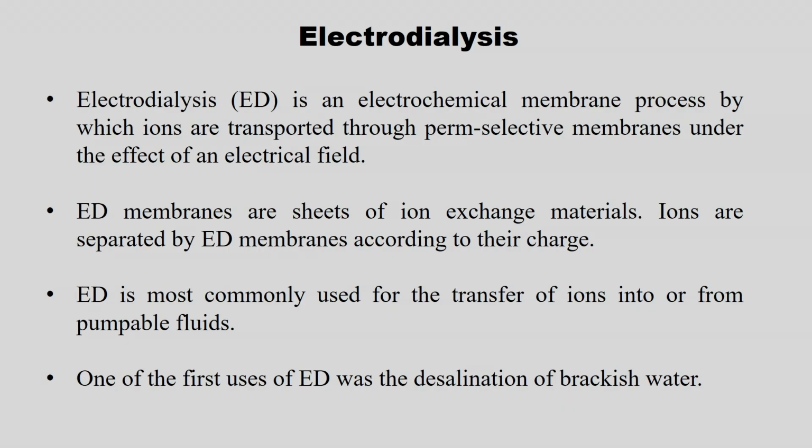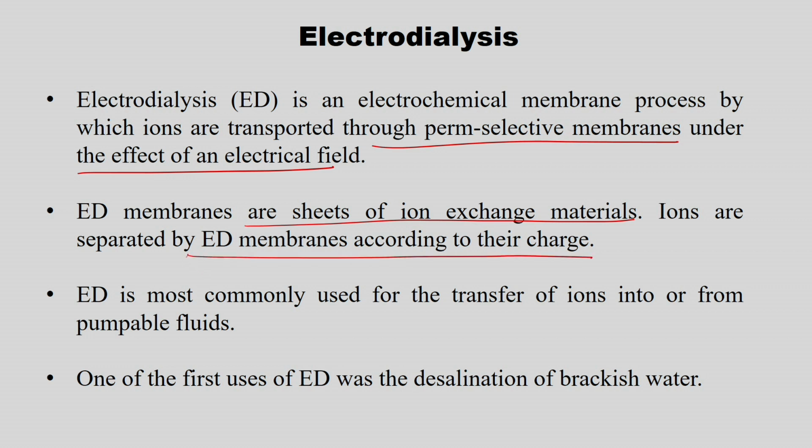Electrodialysis is an electrochemical membrane process by which ions are transported through perm-selective membranes under the effect of an electric field, right. So, the electric field is the driving force here. Electrodialysis membranes are sheets of ion exchange material. The ion exchange material exchanges particular ions only. The ions are separated by ED membranes according to their charge, whether it is an anion or a cation.